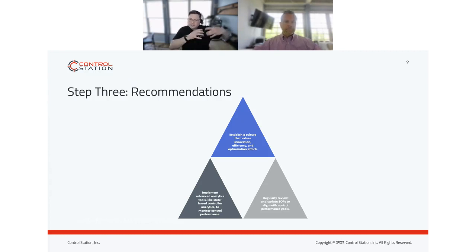But as you start to sustain and you improve and you update your process to be more sophisticated, now you can start to take those KPIs and metrics and really drill down to say, okay, yes, this loop behaves well, but hey, we just brought a new product grade online and now that loop doesn't behave well. So let's analyze individual product grades or recipes or batches to be able to identify opportunities, right? So you're continually sustaining that type of performance.